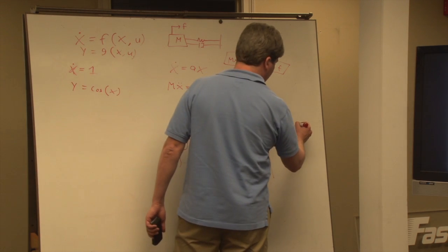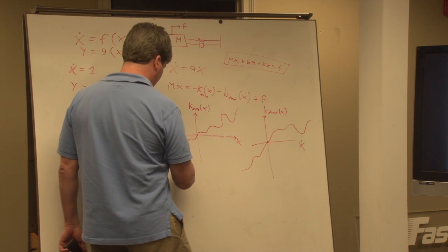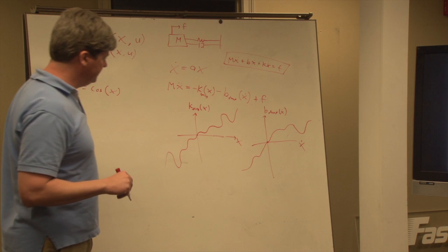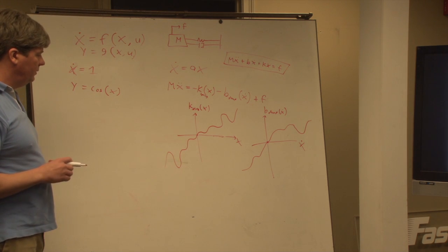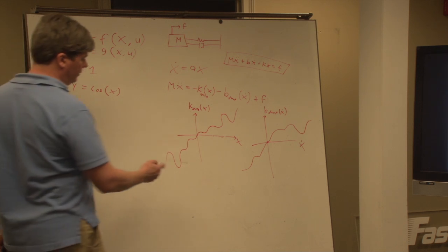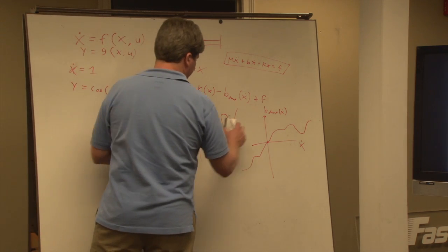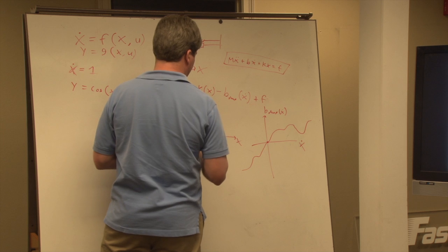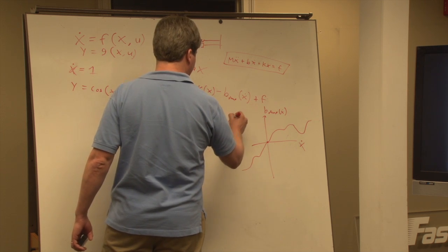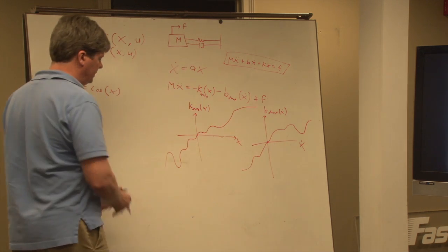Does it necessarily need to be strictly increasing? It doesn't. With the spring, if it's not strictly increasing, then you get detents. If you press it far enough, it will get stuck, and you have to push it in the other direction to make it snap back, and you could actually oscillate about another point where there are detents. For everything I'll be talking about now, it's strictly increasing, so you don't have the detents. Now it could be a stiffening spring, or a softening spring, or stiffening in part and softening in some. But let's just say it's monotonic at least.